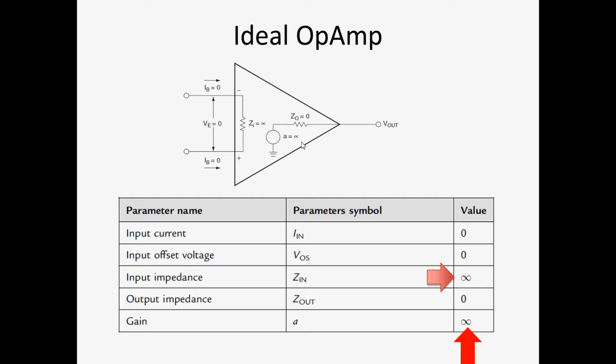So you expect all the traces of the EEG to be flat at zero during the recording. Are they always flat at zero? No. That is because some electrodes have different contact impedance. So the half-cell potential of the electrodes is leaking through differently for all the electrodes. If one of them goes too high, you start to have clipping in your signal.